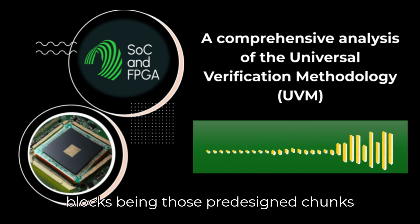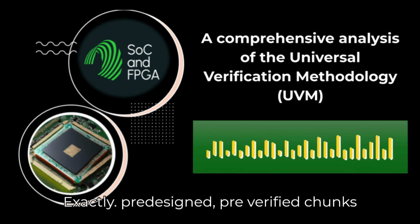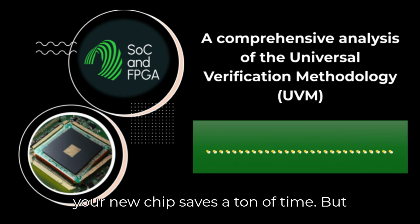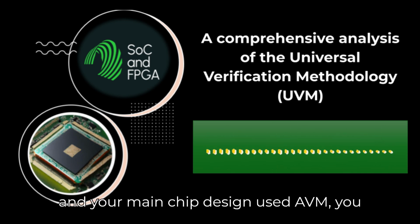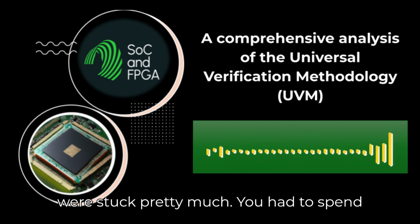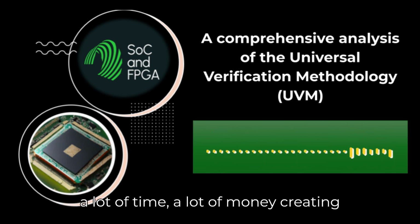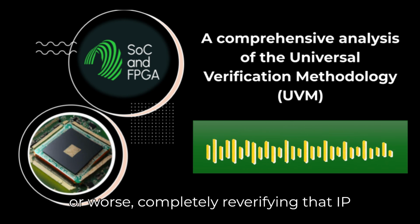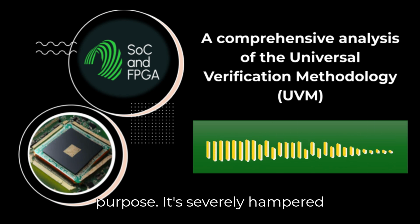IP blocks being those pre-designed chunks, like a Wi-Fi controller. Exactly. Pre-designed, pre-verified chunks of circuitry you want to just drop into your new chip. Saves a ton of time. But if one block was verified with, say, VMM, and your main chip design used AVM, you were stuck, pretty much. You had to spend a lot of time and money creating wrappers to translate between them, or worse, completely re-verify that IP block from scratch. Which defeats the purpose of reuse. Totally. It severely hampered efficiency.